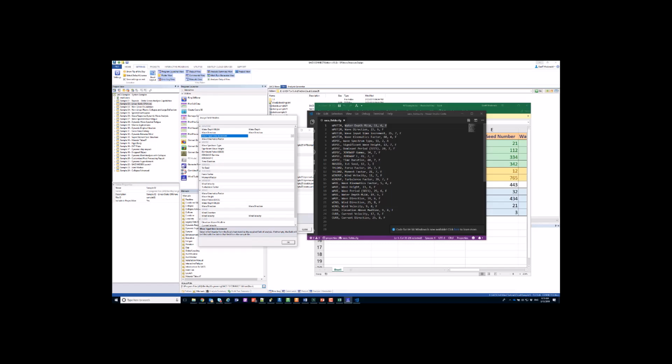We're going to use the random seed number that we have here for this. Wave spectrum type is going to be down here. Significant wave height here. Dominant period. We're not gonna use gamma and C. Those are gonna be just using default values. And I don't think we have a time duration set, right? So we're just gonna use the default value for that. We're going to do no force factor or moment factor.